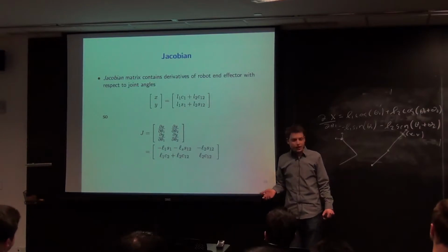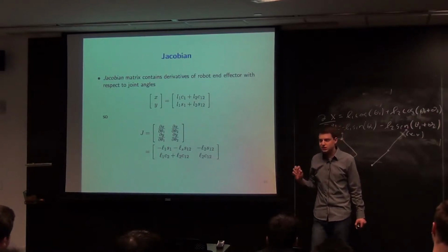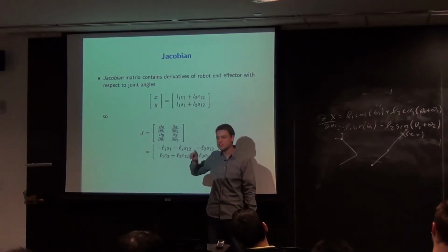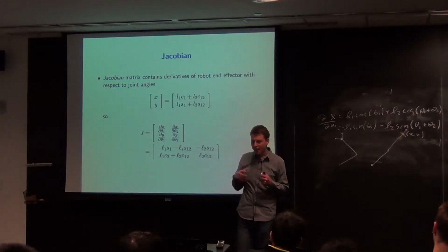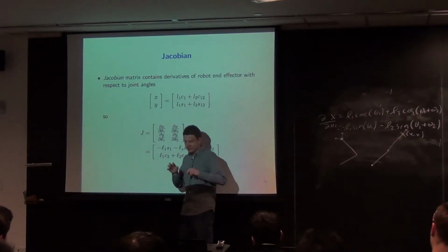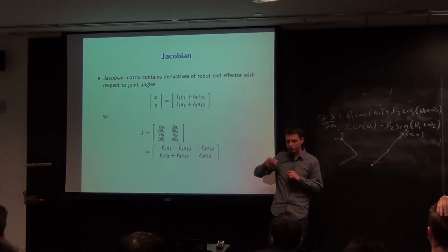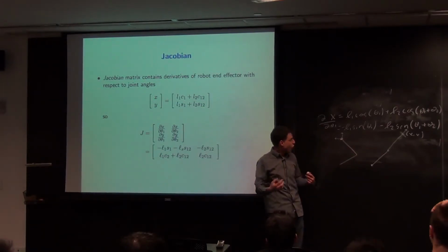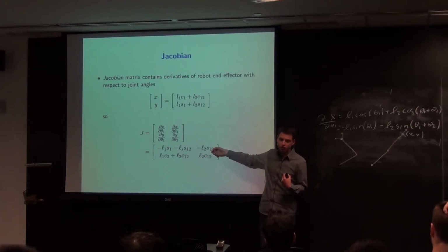But what's nice here is that if you move a little bit in, the Jacobian will be almost singular, telling you essentially you can't move very far in that direction, or rather it would take a very big change in your inputs to get any change in that direction. And that encodes this smooth continuum, from having one solution when you're fully extended to having many solutions when you're in the normal manipulation area. The Jacobian will capture how constrained you are by the eigenvalues of this matrix.